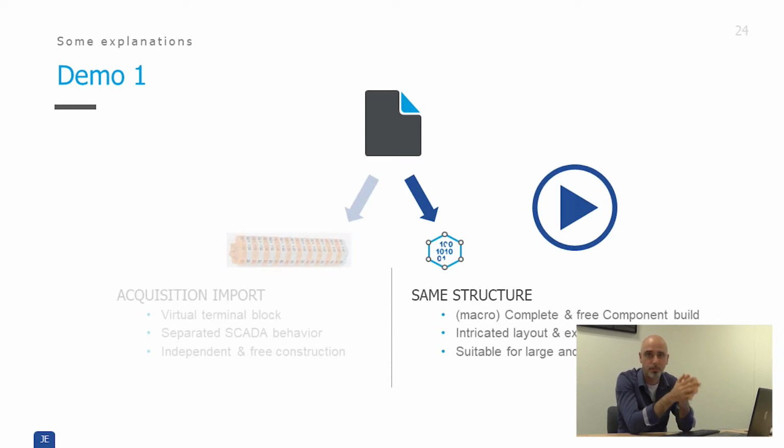The other approach is dealing with the smart Panorama features like automatic filling rules in your components. This way you design the component models you need, containing the behavior, your Scada rules, your features like the user rights, the mimics, the archiving parameters, and then you declare them in the same structure as in the PLC, and you add your components in the nodes.